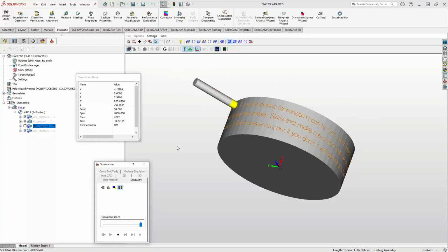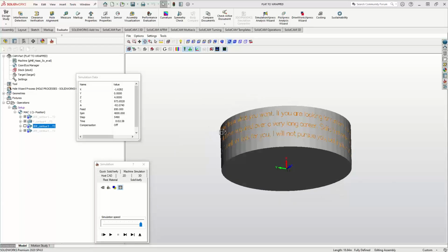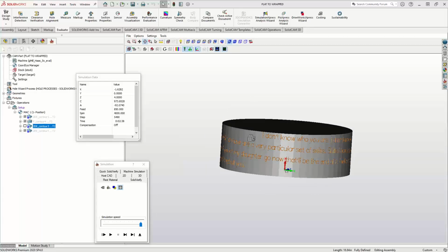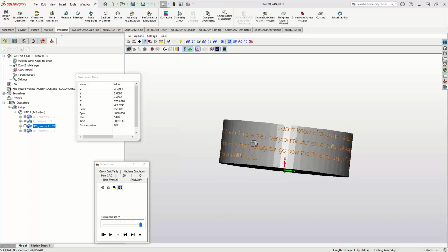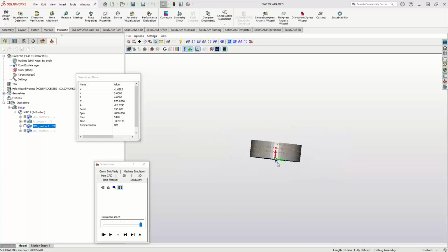So I took that entire quote and I wrapped it around this entire cylinder. And I can do that because, again, circumference versus diameter. I know that I need to wrap this around the diameter, and I know I want to give myself maybe 4 laps around the part. So what I did was I made a sketch that was 4 times the diameter times pi.